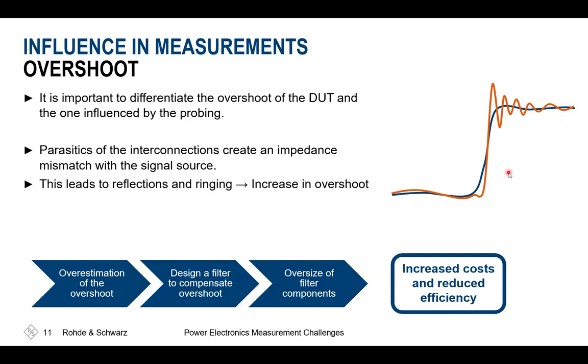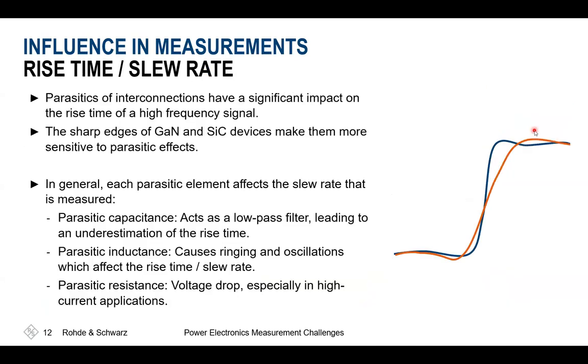Otherwise, it might be difficult to reproduce measurements because you may have exchanged the crocodile clamps for a pincer clip, or used a low quality cable inside your setup for the first run. For the second run, you got another set of cables, and this could already change your measurement results significantly. At the end, the results are also affected by the parasitics inside the package.